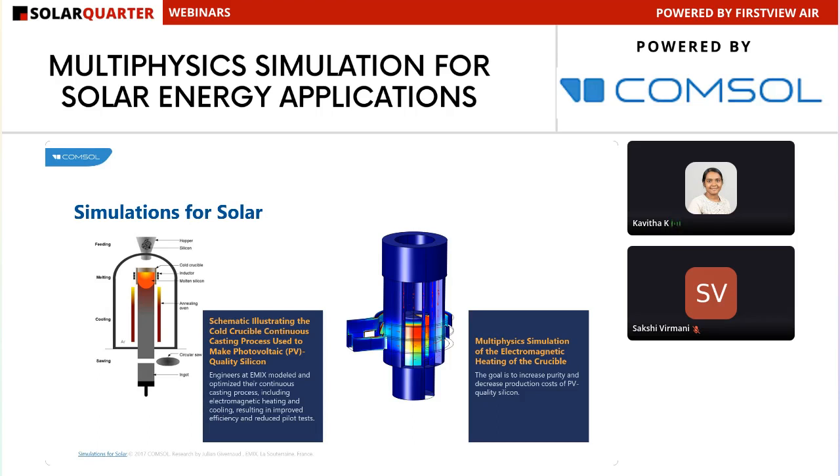The electromagnetic simulations permitted them to estimate inductance and impedance as well as optimize the crucible design to improve the electrical efficiency, whereas the continuous casting simulations allowed for the input of parameters such as the required electromagnetic power, crystallization rate, height of the crucible cooling zone, and afterheat temperatures. The combined results of these studies have led to a compromise between high production rates and low stresses in the ingots.